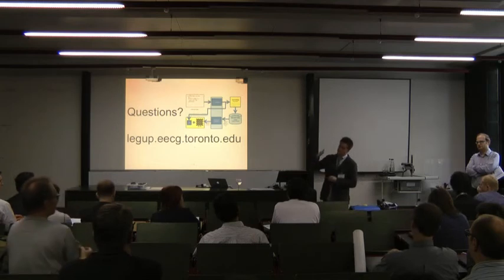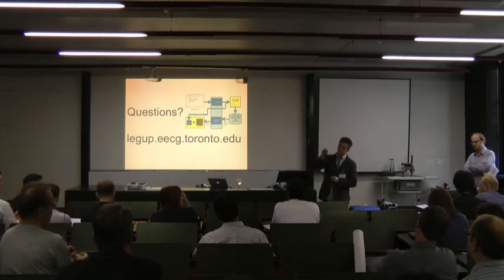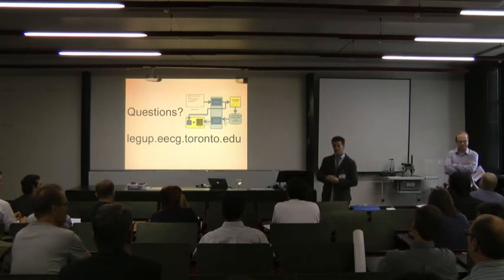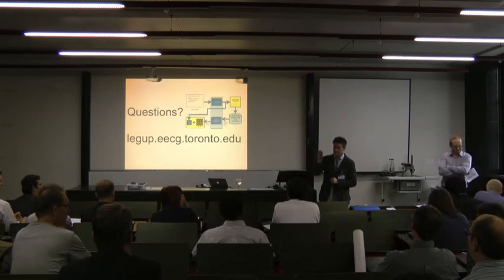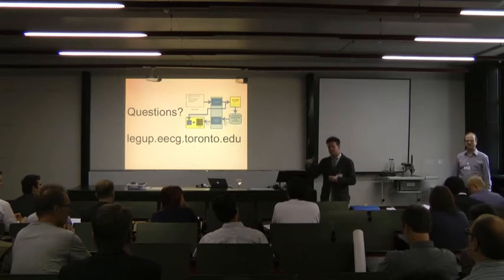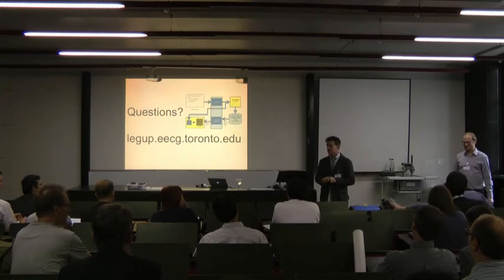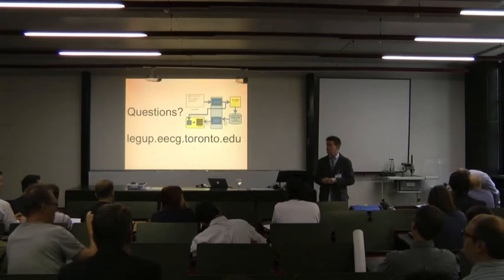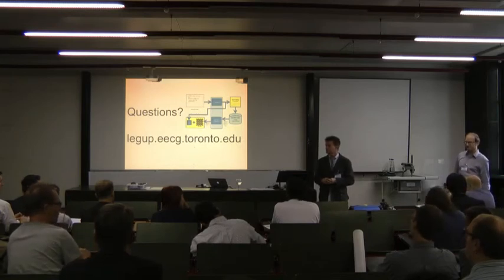Now, in the original results where we had the MIPS processor with LegUp accelerators talking to the MIPS, I didn't show the results here. We did evaluate power in that case, running CHStone on the MIPS versus accelerated CHStone with accelerators. In the original LegUp paper, you can see the power consumption for that. We had more than 10x power reduction. I believe it's 18x power reduction compared to running in software on the MIPS. Yeah, and this will be the key factor for success.